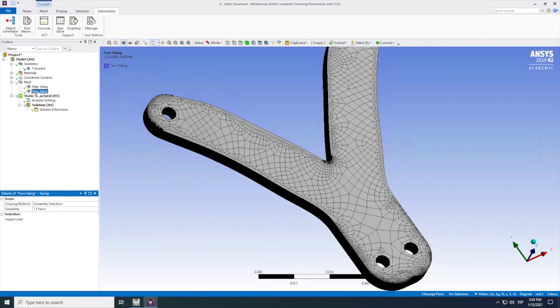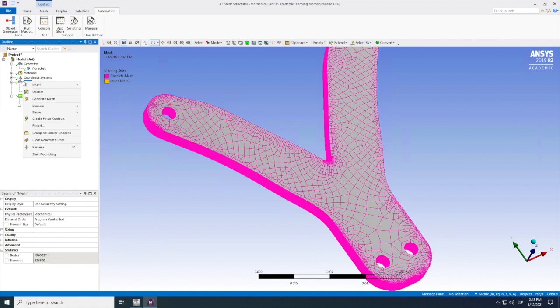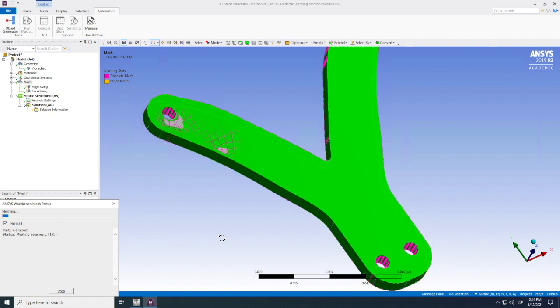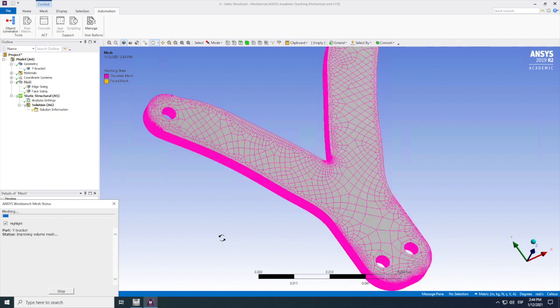Maybe I'm gonna go back here and I'll make it twice as big. That way, generate mesh. And we can reduce the number of elements and the simulation will ultimately be much faster. Which, yeah, this is just for demonstration purposes. Again, we could have a lot more elements in this phase, but that's fine.